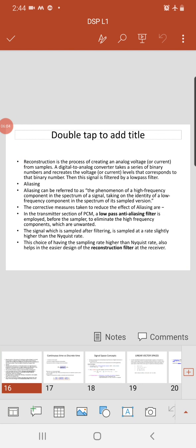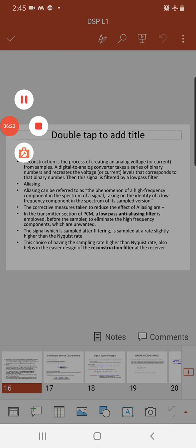Sampling and digital signal processing can be combined to create a high performance sampler. For example, CD players use an oversampling approach, which involves sampling the signal at a very high rate and then downsampling it to avoid the need to build high precision converters and filters.